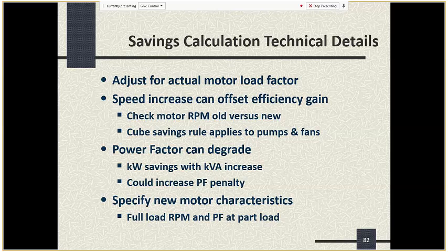If I recall, Larry, except for maybe the small HVAC stuff that you changed out and the chillers that you changed out, you didn't do a lot of motor replacements on the fans, did you? We actually did at H&L, Dave, primarily so that we ensured that we had induction rated motors for use with VFDs. Right, so you had to replace motors to make sure they would work. And I'm assuming when you did that, you tried to match the RPMs of the old versus the new. Yes. Yeah, but that's sort of an important factor.